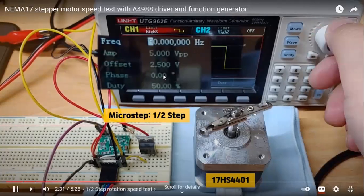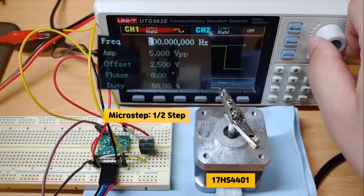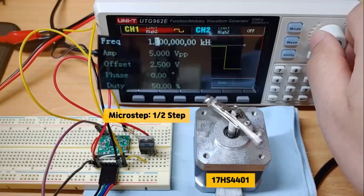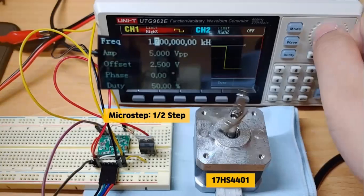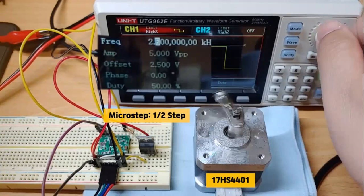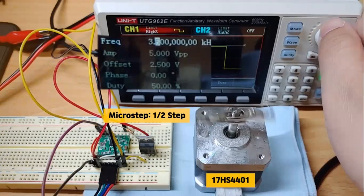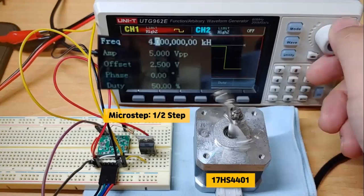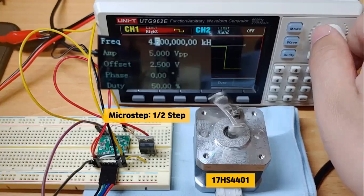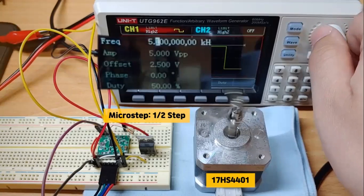So this is half step. So as I told you, you can rotate the stepper motor at an angle of 1.8 degree or at an angle of 0.9 degree. So it depends upon you how you are rotating the stepper motor. If you are rotating in 1.8 step sequence, it will rotate at a faster rate. When you rotate at 0.9 degree rotation, the stepper motor will rotate at half speed.